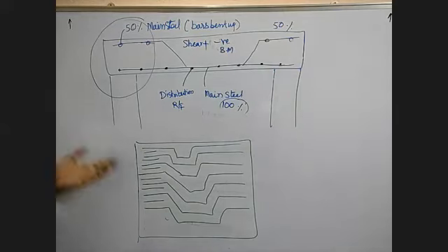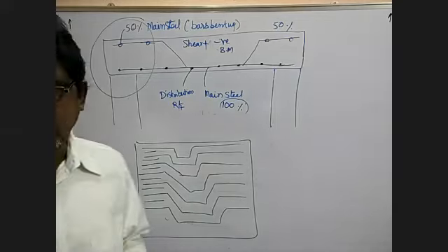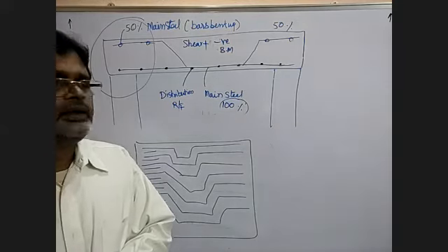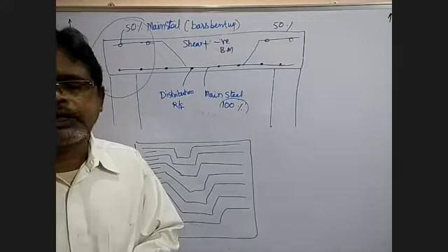Okay, so this is regarding the theory of one-way slab or two-way slab. Only the design steps make the difference. One-way or two-way, depending on ly by lx being less than or greater than the limit. Now this is regarding the slab theory. Tomorrow we will solve the one-way slab and we will try to solve the two-way slab also.